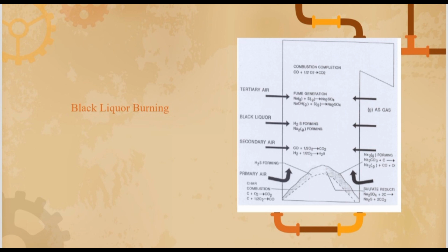Secondary air is located above the primary and below the liquor guns. It may be on two walls or all four walls, and there may be more than one level. Tertiary air is introduced above the liquor guns, normally on either a two-wall interlaced pattern or concentrically. There are now units operating with quaternary air or even more air levels. That's all for me. Thank you.